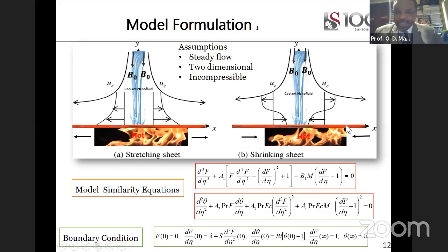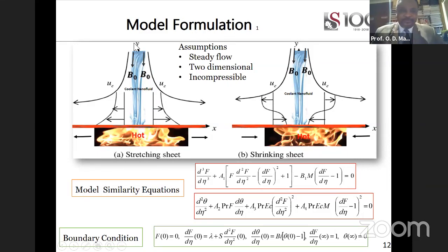The plate is shrinking, the surface is shrinking because of the heat, but this fluid is pouring on it, and a magnet is applied to make sure that the heat is taken away. So all this, we want to look at it. And we assume the fluid that is flowing is steady flow, two-dimensional, incompressible. So to model this, you use the Navier-Stokes equation. It's a two-dimensional flow in X and Y. You have your velocity U and V. It's incompressible. You assume the fluid is Newtonian.